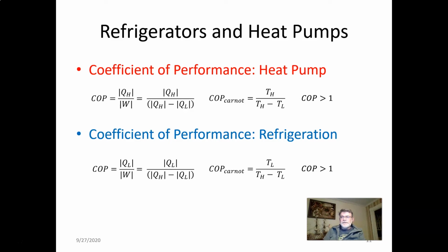So it roughly compares the heating capacity of a heat pump to the amount of electricity required. Here are some formulas that we are going to use during the lab. You see the COP is defined by this formula, Q hot divided by Q hot minus Q cold, for the heat pump. And the Carnot is this.